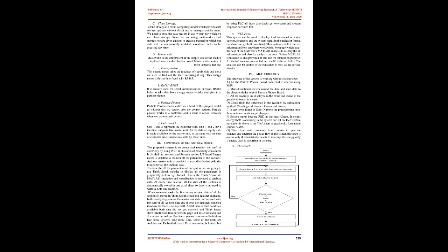Here at the ThingSpeak site, MATLAB simulation and visualization is provided to analyze data. At every time interval, all the data of the system is automatically stored in an Excel sheet, so there is no need to write and note any readings. When someone hooks the line in any section, data of all the sections is stored in the ThingSpeak cloud and the data gets analyzed. In this analyzing process, the master unit data is compared with the sum of all sections' data, and if both data match, it means there is no theft. If there is a theft condition, both data do not match, and ThingSpeak shows the theft condition on the website page, a red indicator, and the alarm gets turned on.